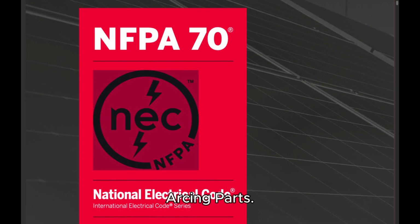110.18 Arcing parts. Parts of electrical equipment that in ordinary operation produce arcs, sparks, flames, or molten metal shall be enclosed or separated and isolated from all combustible material. Informational note: for hazardous classified locations, see Articles 500 through 517. For motors, see 430.14.